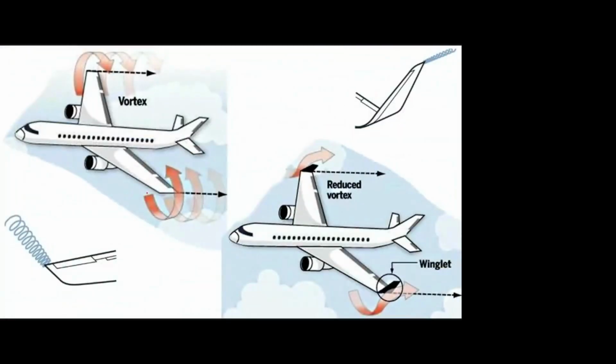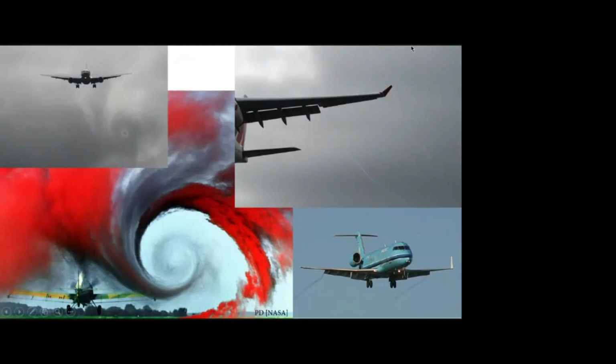Without the winglet, there is a large side leakage flow which causes a big wingtip vortex. But here most of the flow is deflected rearward. It cannot go onto the upper surface. So here we are getting a very small wingtip vortex. So this produces less induced drag. That is another purpose for which we use the winglets. You see here, there is only a small wingtip vortex from the wingtips.